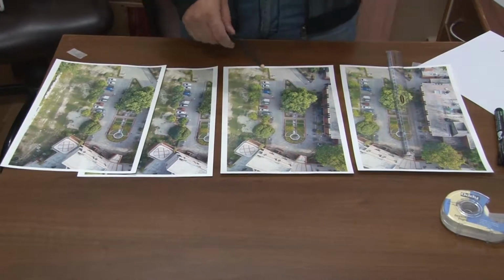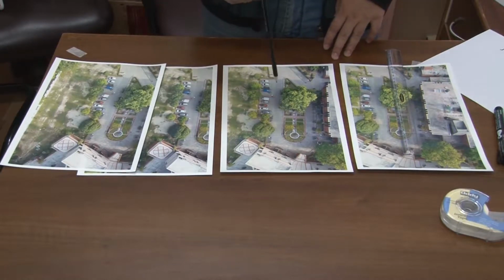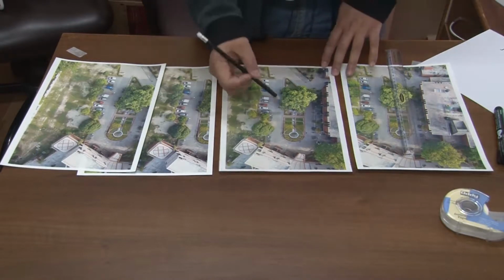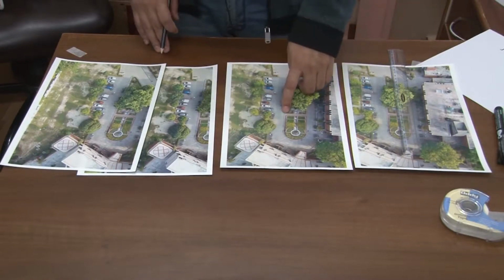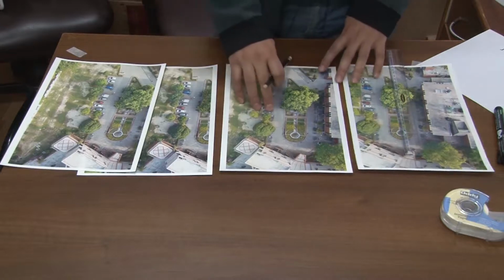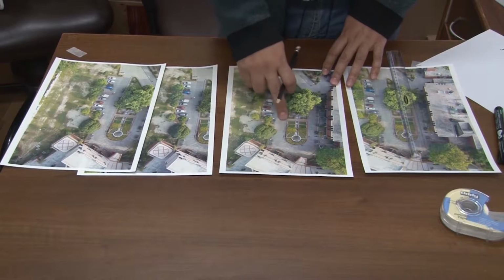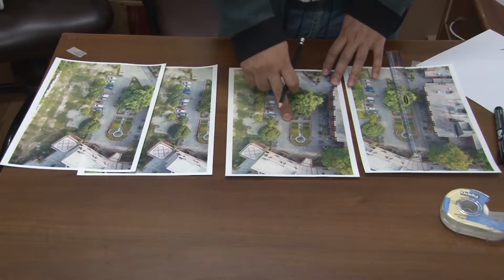The lens will work as a central projection from where the rays will lie perpendicularly over the ground, and it will pierce the principal point or the nadir point. So in this case, because this is a true aerial vertical photograph, your principal point, nadir point and isocenter will coincide.